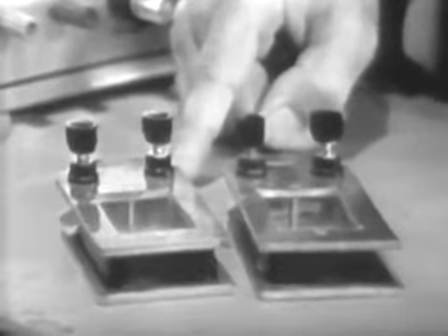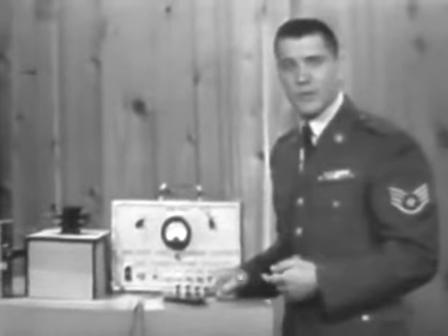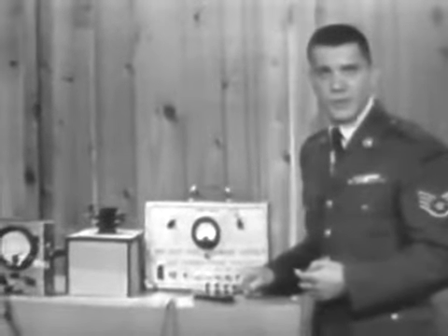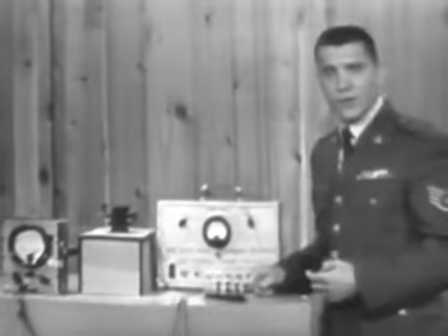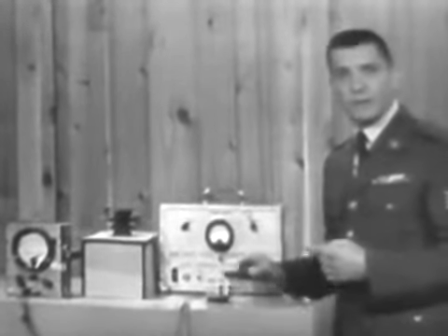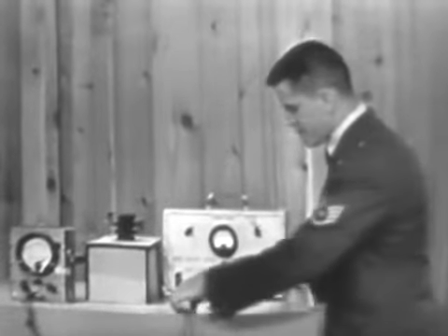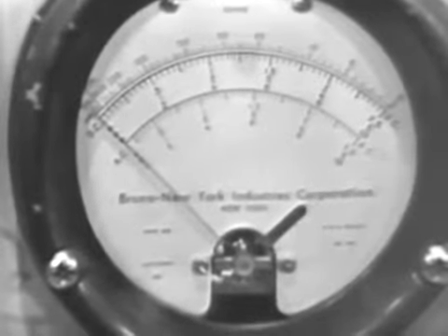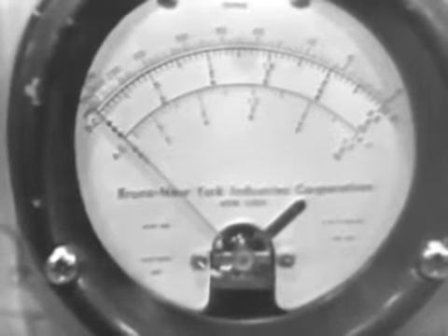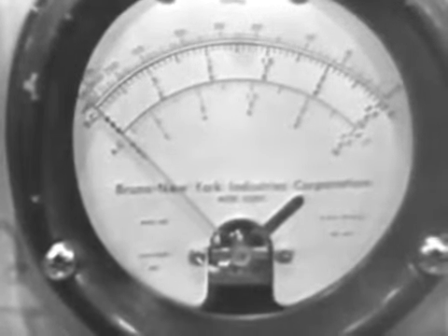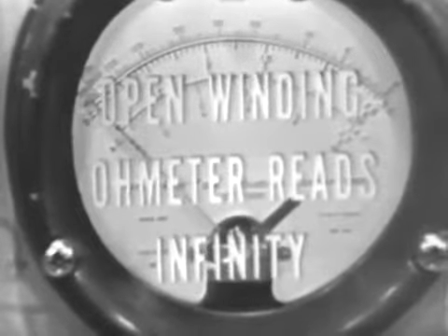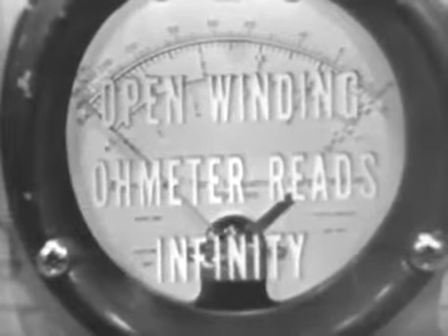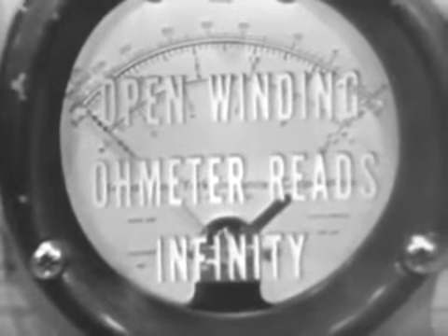The big difference in these 2 windings, however, is that one of them is shorted and one of them is open. So let's use our ohm meter and see if we can tell which is which. Now remember, the PSM6 has already been set up to read resistance on the ohms times 1 scale. So let's go ahead and check the resistance of the 150 turn winding first. If we'll take a look at the meter now, we'll see that it reads infinity. Well, since the PSM6 always reads infinity for an open, this then indicates that the 150 turns winding, the one I'm now measuring, must be the open winding.